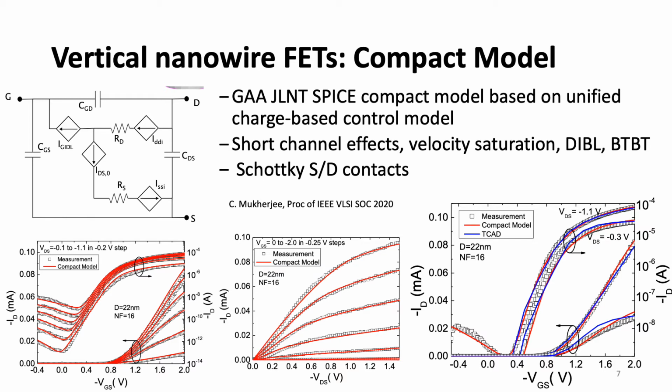Schottky contact formulation at the source and drain access regions is also included through thermionic and leakage current sources in the intrinsic transistor electrical equivalent circuit. The compact model has been calibrated against both experimental and TCAD simulation data, showing good model accuracy.